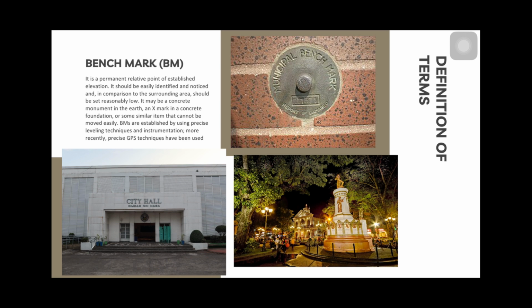In practical surveying, a benchmark is a point with a known elevation that we can trust when performing differential leveling. For our lesson today, we don't have the exact official benchmark data for Naga City, so surveying teams in the Philippines often rely on records from NAMRIA or local engineering departments to find that information. But to make things relatable, let's use the Naga City Hall as our example reference point.